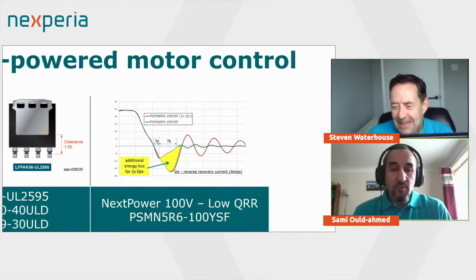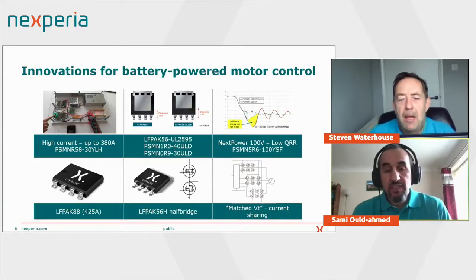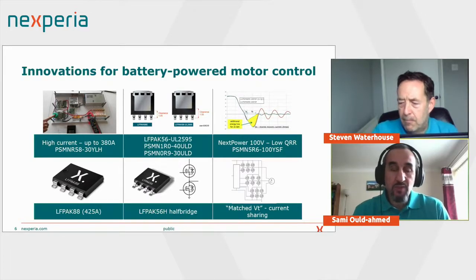So as we mentioned, first of all, with regard to the VDS rating. Now, we mentioned that normally the VDS rating of the MOSFET is chosen to fit the system voltage levels. The system voltage levels tend to be 80% of the rating. But then again, other designers may choose a different approach.